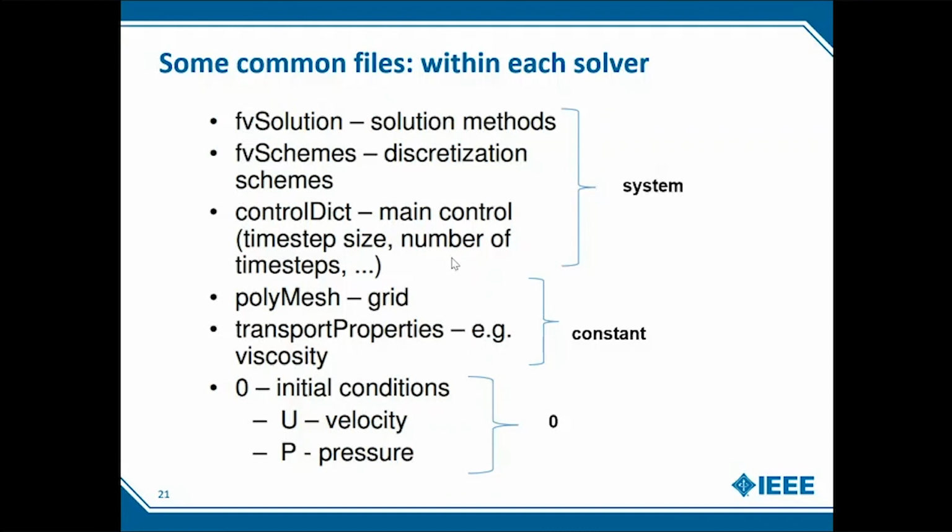So in grid independent study, whatever parameter is of your interest, for example temperature, you see how the temperature changes with different numbers of mesh elements. So your value will change drastically from a very low mesh to a very high mesh. So grid independent study is basically to find a mesh count after which your temperature value does not change. So what that means is you have found your optimum mesh count. If you go higher than that, it just increases your computational time, but it does not improve the accuracy of your solution. I hope that's clear.